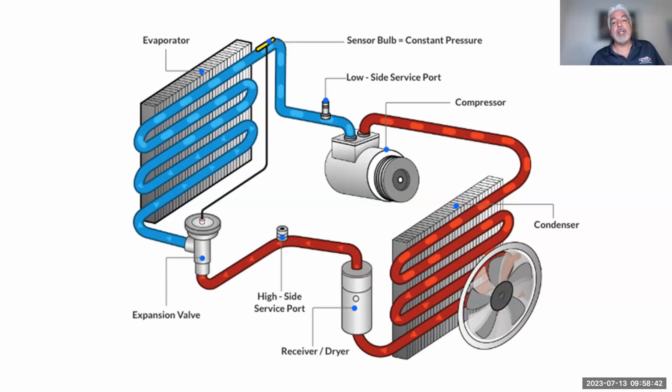But like I told you already, if you have an infrared temperature probe, you can shoot it across the condenser if you can get to it. And at that point, you could see where the leaks are at, because it'll tend to run hotter or colder there. I'll ask that question here again. But yeah, you'll see those spots where the leaks are at within the passages.